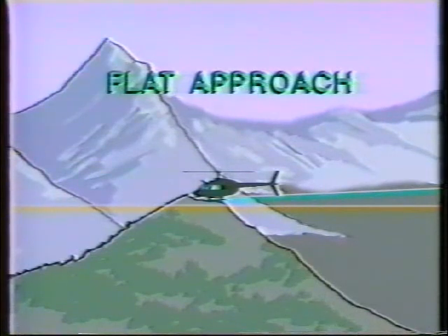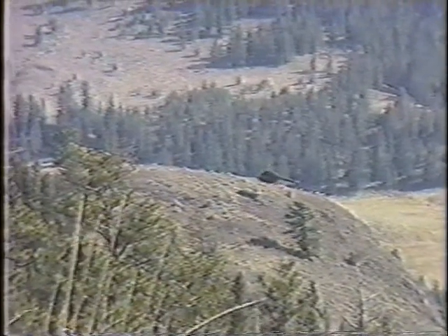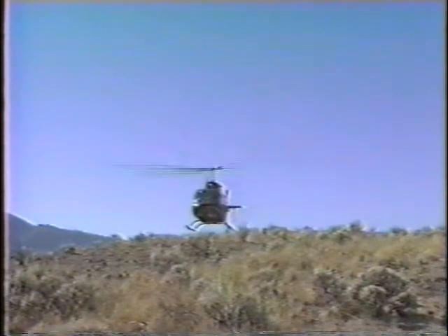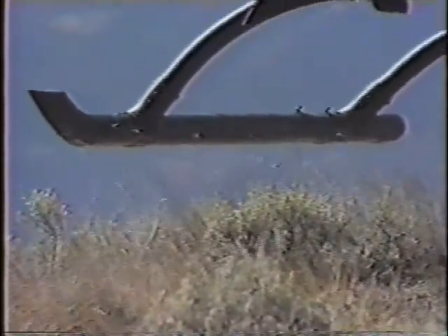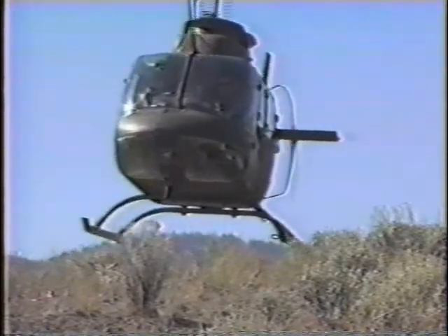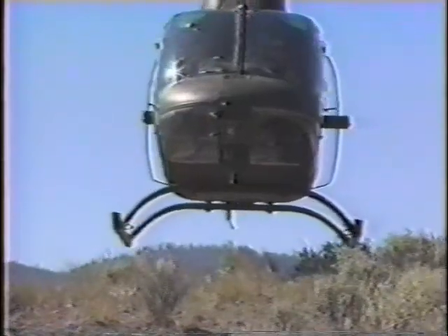It's easier to reduce your ground speed, and you can easily land at the termination of the approach with no large collective change. Even though your flat disc, low ground speed, and good collective position make it unnecessary to hover on landing, it's still a good practice, giving you time to stabilize for a smooth touchdown. The low hover should be 6 to 12 inches above the ground on the landing point or just shy of it. In high mountains, you may not have the power for a low hover. That's when you'll be thankful for learning the flat approach.